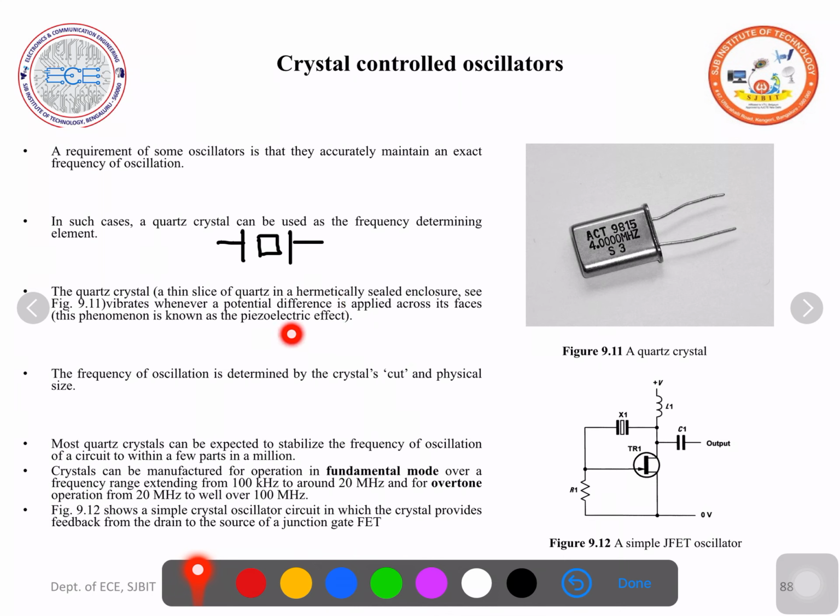The phenomenon of piezoelectric effect is when you apply a potential difference between the opposite faces of a quartz crystal, it vibrates at a particular frequency. That frequency of oscillation is determined by the crystal's cut and the physical size. Whenever you need accurate frequency of oscillation, then we will go for the crystal controlled oscillators.